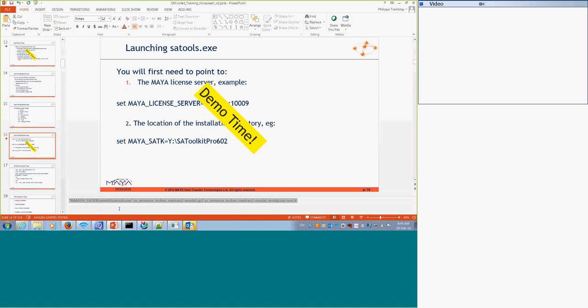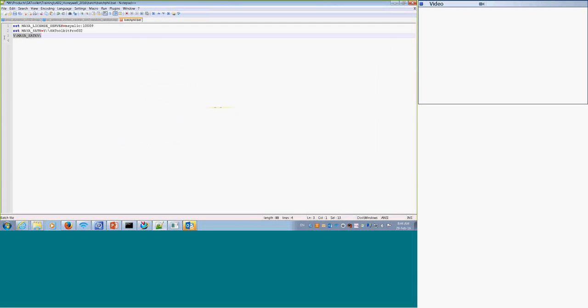To make things faster, I'm just going to paste this line here. Path to my executable, my file name, my definition file name, and a new name. I just put test. And then the code: I'm running the modal summary, so it's code 8.